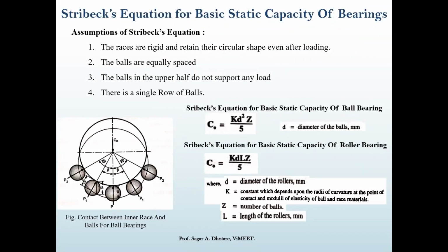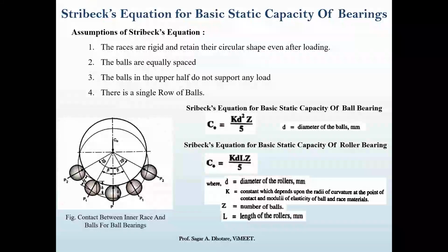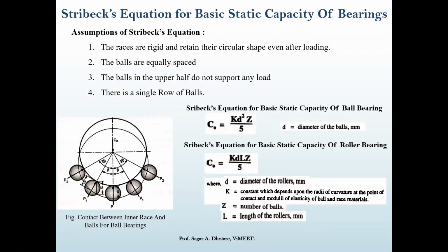Then the second one, the balls are equally spaced. And the third one, the balls in the upper half do not support any load. So the upper half portion will not take any kind of load or support. The lower one is directly engaged with the load carrying capacity.